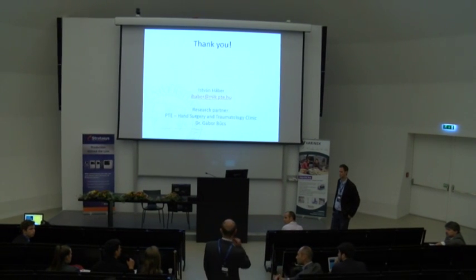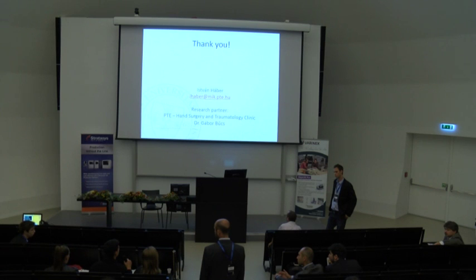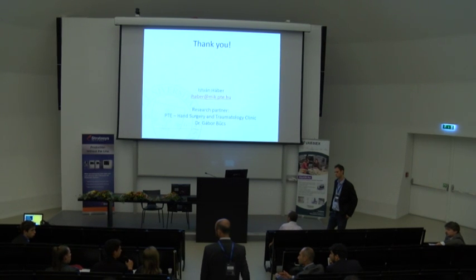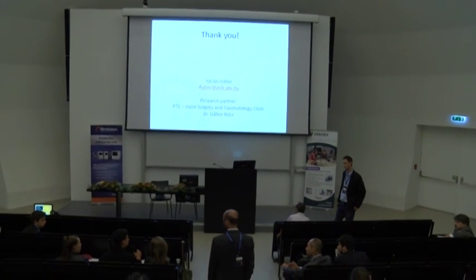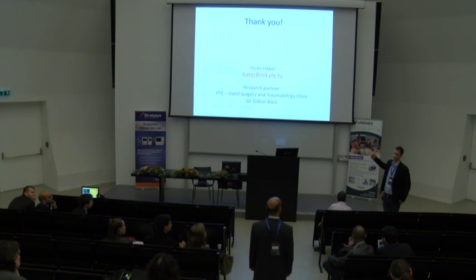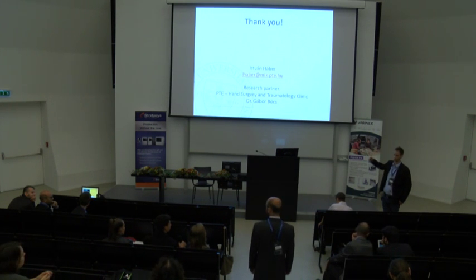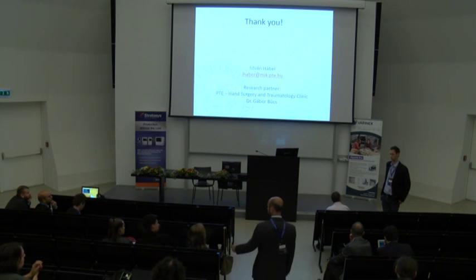Just one question about the material concern. What materials do we use, because the body is highly intolerant of materials, but certain materials, and you are saying that you should 3D print these materials. So what materials would you use? Those materials, which I listed, are basically used in implant manufacturing. We can 3D print those already with these techniques, as I also listed there, the selective laser or electron beam melting or selective laser sintering. These techniques are good for that.